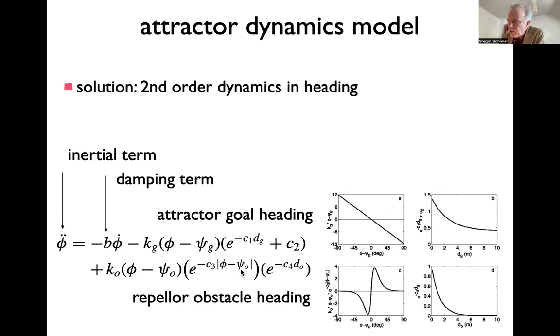So that's very natural. What they didn't do is take into account that these are angular variables, right? So in our robot models, we put a sinus in function of these terms, and we actually write this as a cosine of that thing. And we have to lift the cosine to be only positive. Similarly, we'll put a sinus on this term. And that's because it's periodic. So in the robot, that's really important because the robot goes in all kinds of directions, so it also sometimes might go in the opposite direction of one of those contributions. In their modeling, the experimental paths they had for the human were quite restricted in how much they turned. And within the little turning that they got, there wasn't really a big difference between the sinus and the cosine term. That's why they got away with that linear function, which is easier to handle mathematically. Okay, so if there's a possibility for turning multiple times, you need the sinus in this case.